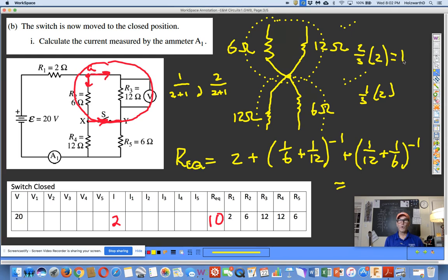So this is going to be 1.33 amps flowing through the least resistant path, and the most resistant path is going to get the balance of 2. So that's going to be 0.67 amps. Excuse me that I'm not writing out the units, but current is measured in amps, so both of these are in amps. Sorry about being a little sloppy here.